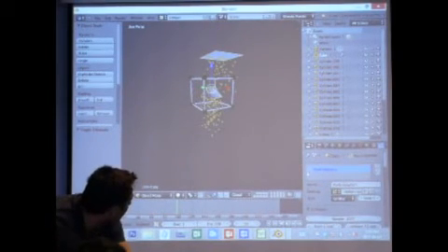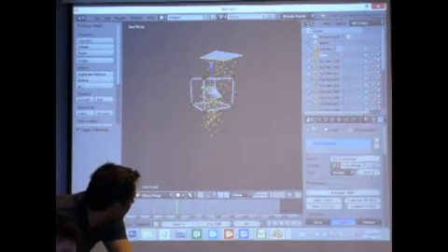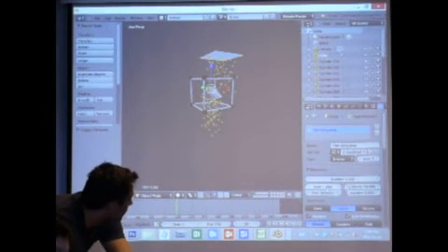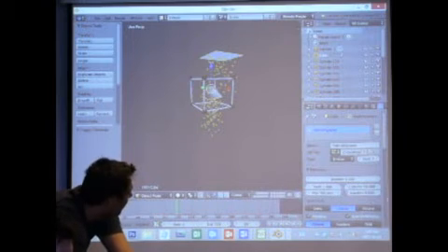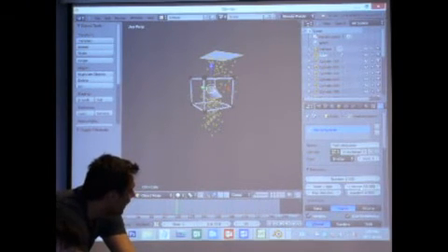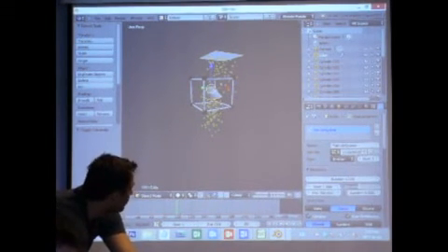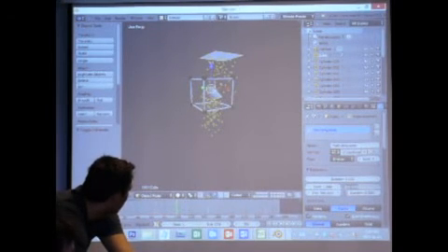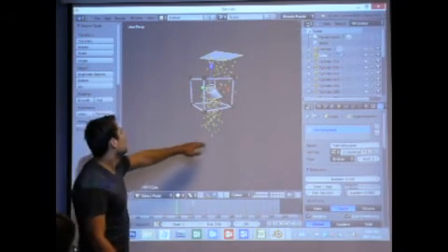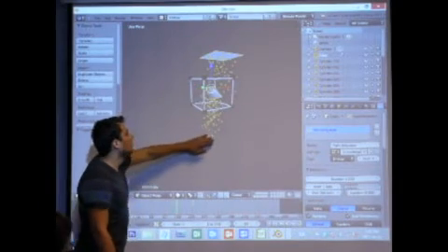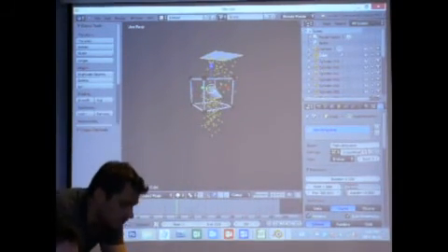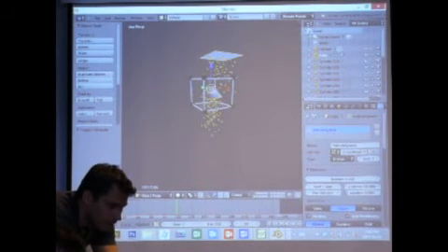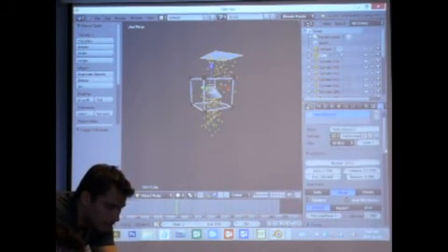And they have their own settings. There's the life, where it starts, the frame time. So it starts with the first frame and ends at the 200th frame, just below 10 seconds. And you can change the lifetime, so how long you want them to last. That's why they stop here. Stop at 50 frames, you stop the animating. So you can actually keep them going on forever.